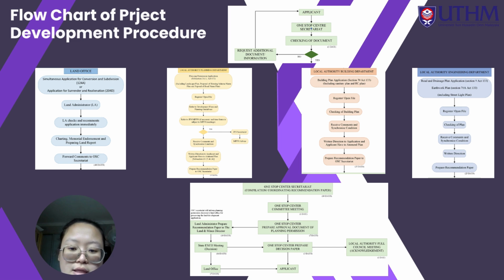The local authorities planning department conducts a thorough examination of the proposed development. The planning department may require the applicant to submit additional studies or reports such as traffic impact assessment. After a detailed review and any necessary revision, the planning department grants planning permission and forwards the project to the